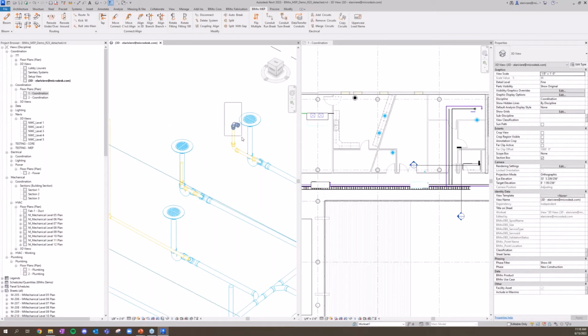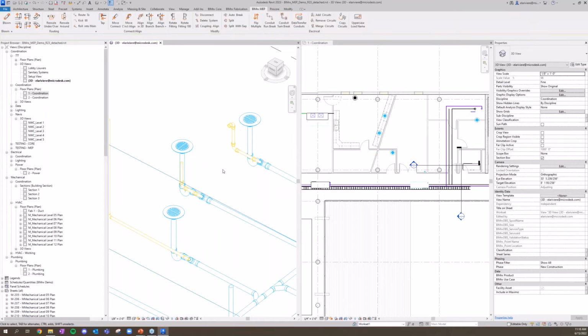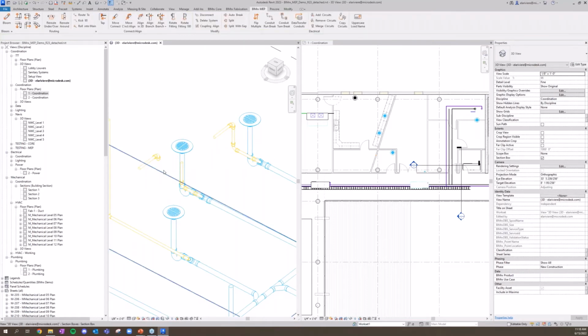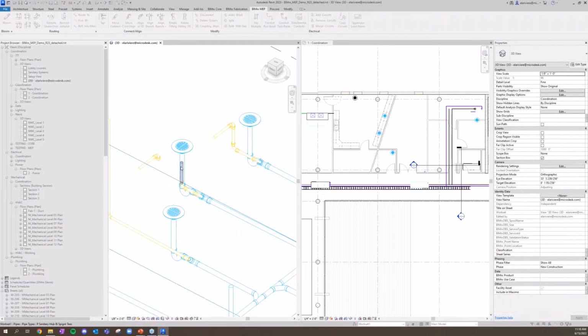You can grab one of these, do that rotate fitting, 90 degrees. I can bloom that one out, give us an extension there, grab those elements right there, copy these along, place those over here again. Let's do another move connect to bring these elements together. And now we're sitting here with a couple systems.